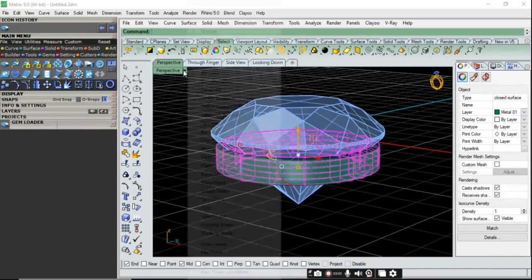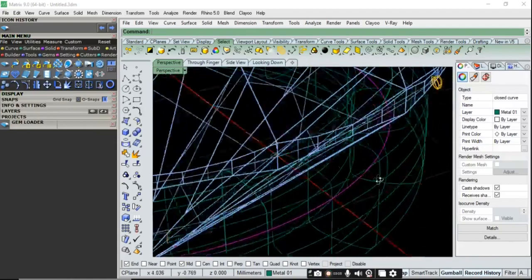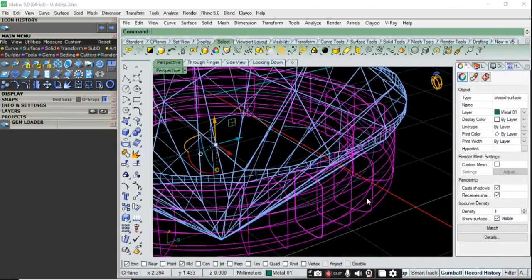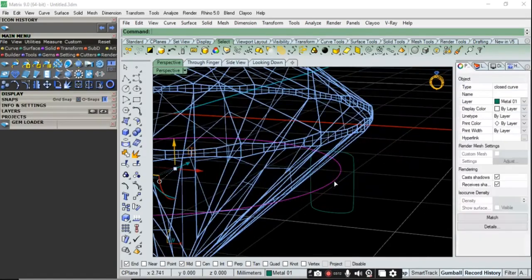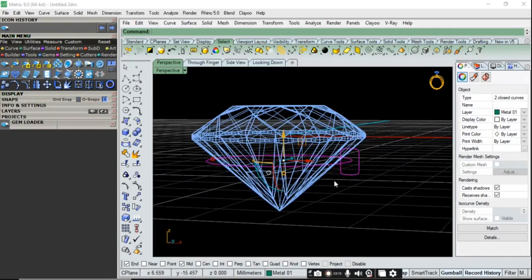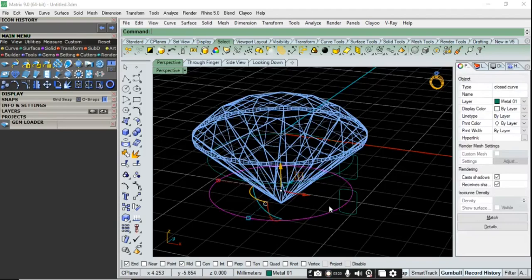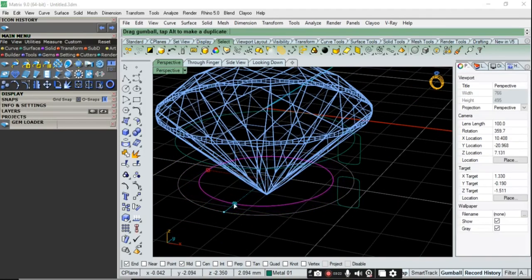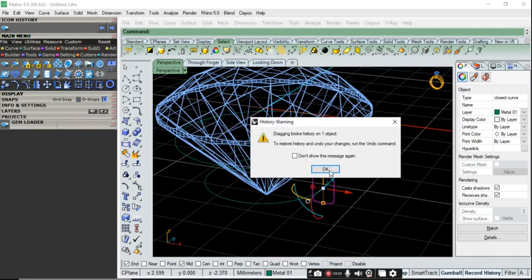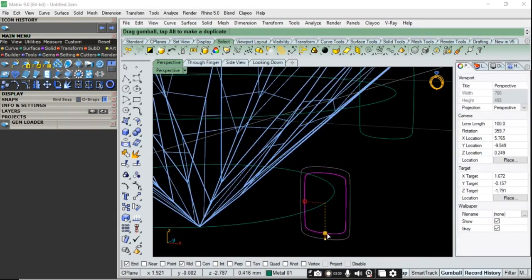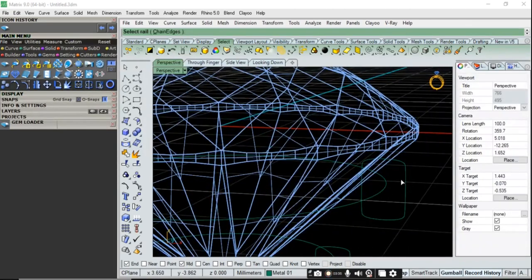We also need another rail because we have 2 rails, so we need another copy of the curves. So now use Ctrl plus H to hide any object. Now select both the curves, and by keep pressing Alt key, drag down the gumball option. It will create another copy. Now scale it down inside the circle and then drag the profile on the curve and scale it as per size or as per our dimensions.